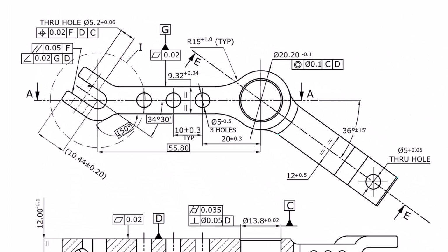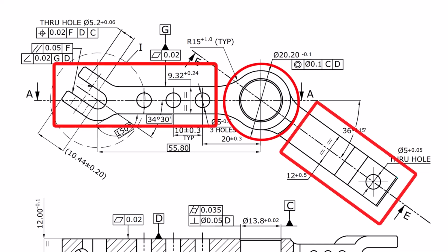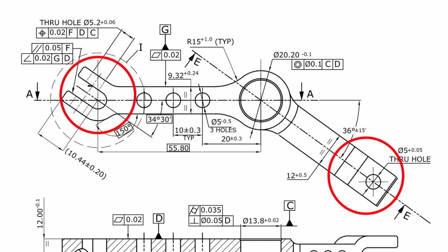Look carefully at the largest view shown on this drawing. This is the principal view of the component. If I were creating this part in SolidWorks, CATIA, Creo, Fusion 360 or Siemens NX, this is the view I would probably study first because it gives me the maximum amount of information in a single glance. Notice how much we can already identify. We can see the large circular boss, identify the long connecting arms, recognize the forked end, and we can also locate several holes and curved profiles.